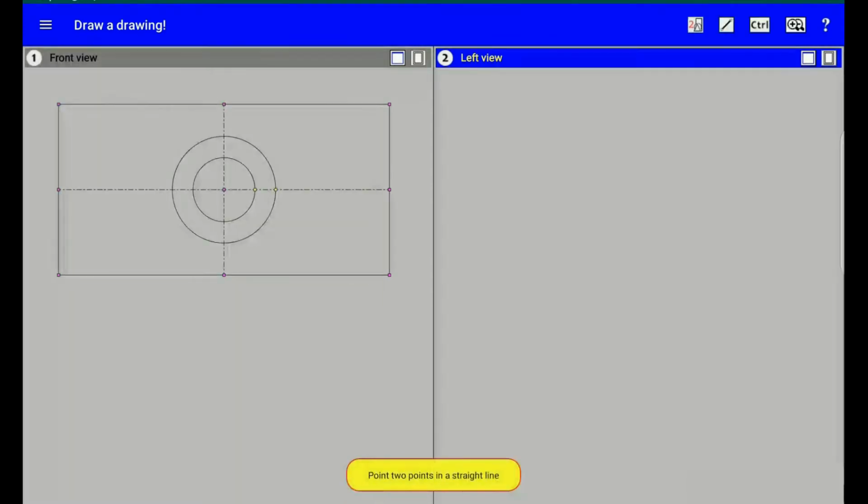Select the straight line segment graphic item. Press the Control button to create supporting points at the same time as creating lines. I put graphic elements without worrying about the accuracy of the positioning of the points. When you need to use an already existing point, turn off the Control button.